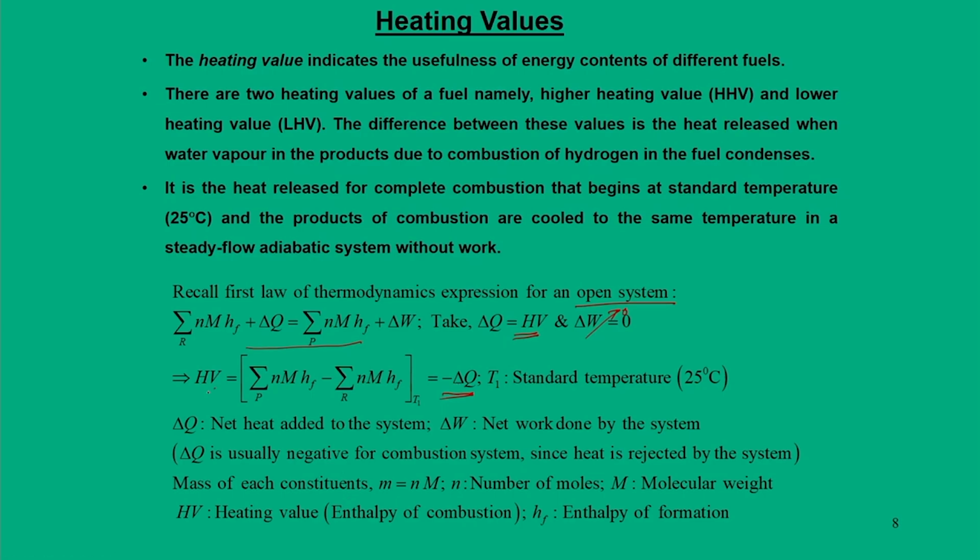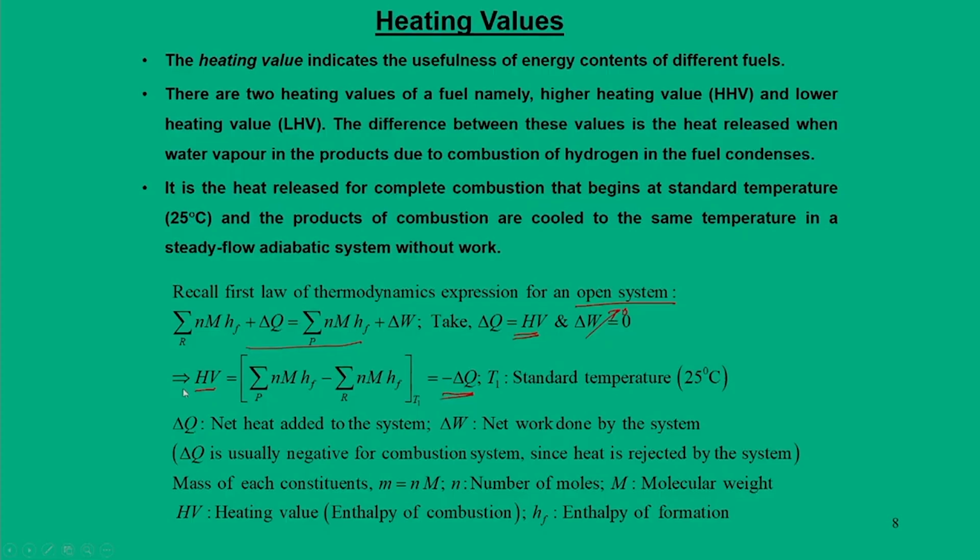So, that is the reason the heating value is just the negative of the heat of combustion, just to ensure that the heating value is always treated as a positive quantity. Heat of combustion is mostly negative for exothermic reactions, but when you define the heating value, it is just the negative of that heat of combustion, so that the heating value is always interpreted as a positive quantity.